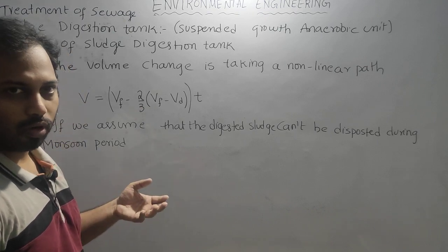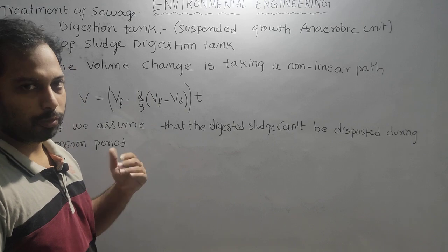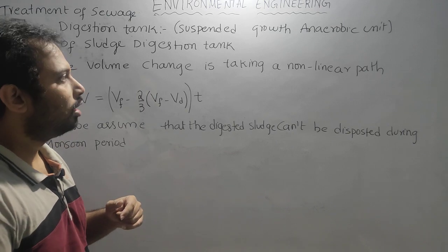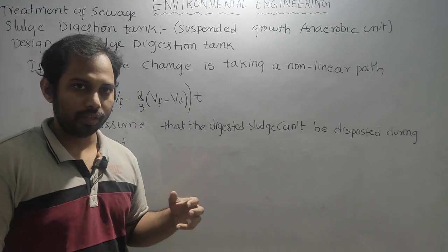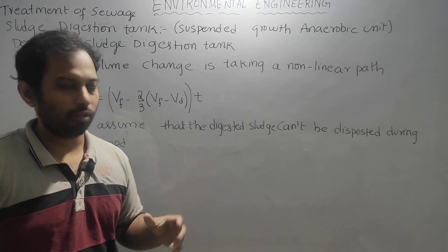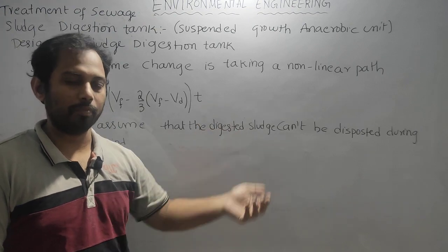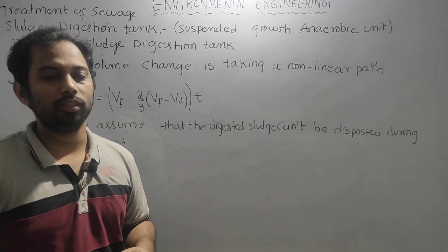If the BOD is high, we send it back into the system. If it is fit for disposing, only then do we call it disposal. How to manage that disposal, we will discuss in the coming topic, which is the next step of taking care of the sewage.